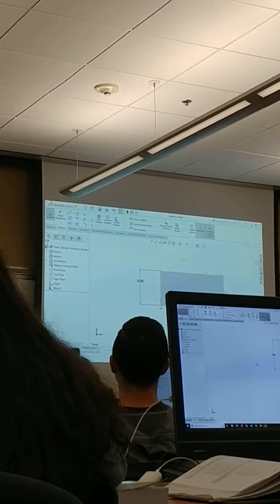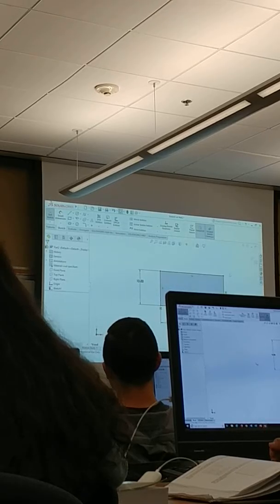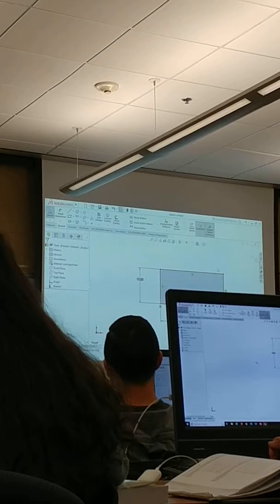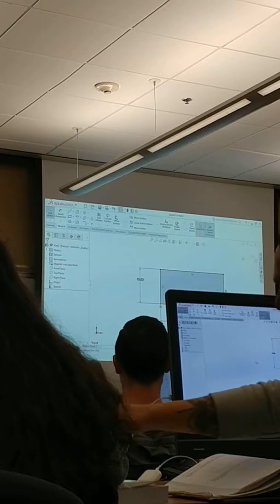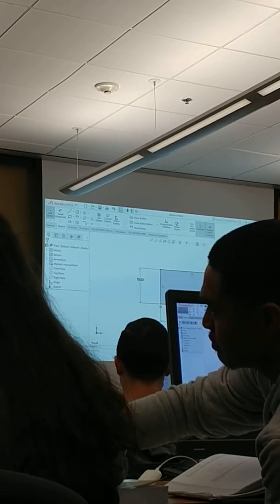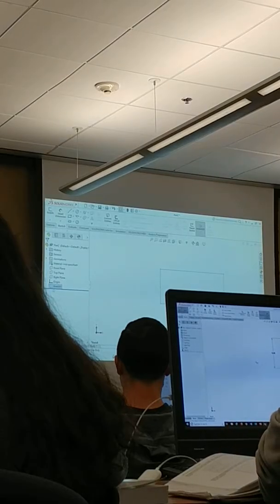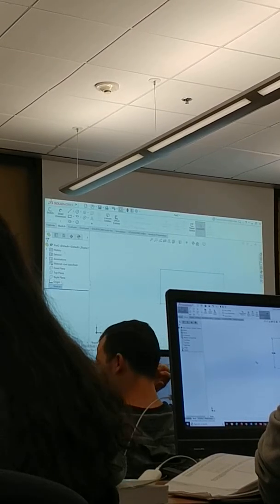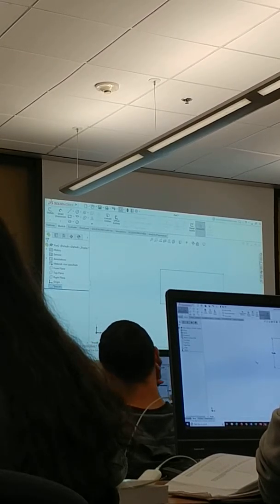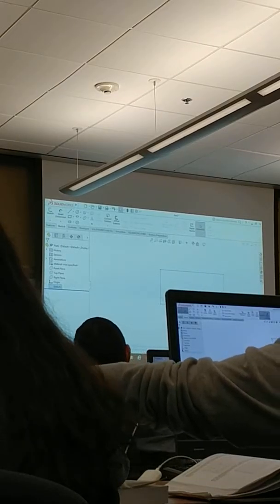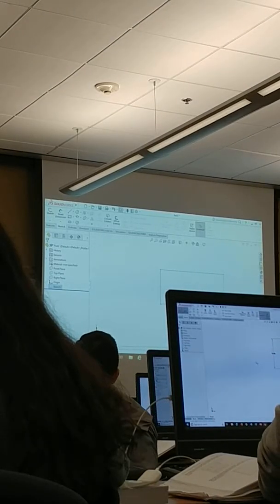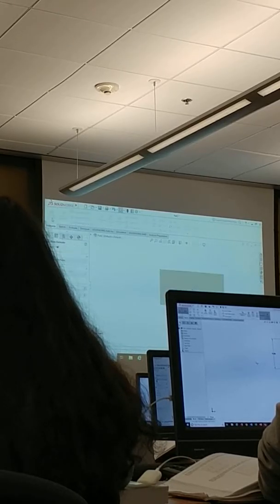Okay, so what I'm going to do is remove that. And there are two options for getting out of the sketch. You can click here. And now you can see you have a sketch. That's your first kind of feature in your feature manager. It's not really a feature yet, it's just a sketch. To make that a real feature, we have to go to Features and extrude it. I'll do that again.